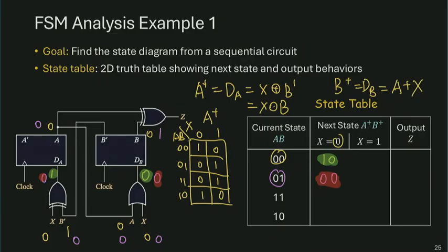And you can use that information to immediately fill out this entire row, like half of your next state column in the state table. Right? Instead of doing them in the evaluation one by one, we directly do an evaluation based on the Boolean expression and then convert that into a K-map. And you'll see the table also follows the same K-map order, which allows you to directly map an individual K-map into two separate columns in the state table. Those are the two columns for A plus, when X equals 0, X equals 1. I just got to do the same for the B variable.